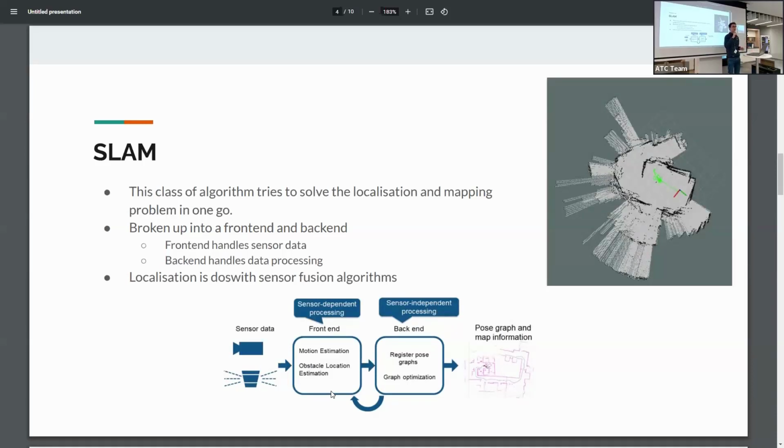So for example, you can be getting wheel data from your wheels, and your right wheel might say, hey, look, I've moved forward 5 rotations. And your left wheel might say, hey, look, I've moved forward 4 rotations. But they've actually both moved forward the same amount of rotations. So now your robot thinks it's on the other side of the room, but it's actually here. So it's really important to try to solve this.